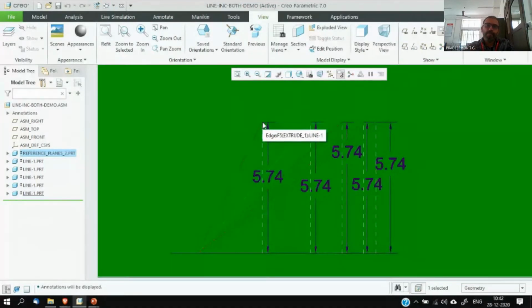The angle with HP in that case is either that 45 degree or the 60 degree, whichever set square you have taken. Depending on that one, the angle changes. But still, for a particular set square, it remains the same. If you have taken the 45 degree, the angle with HP is 45 degree. So in that case, the height of the second endpoint can be found out using that length multiplied by the opposite side, that is sine 45. So that trigonometric function remains the same, the height, as long as the 45 degree doesn't change.